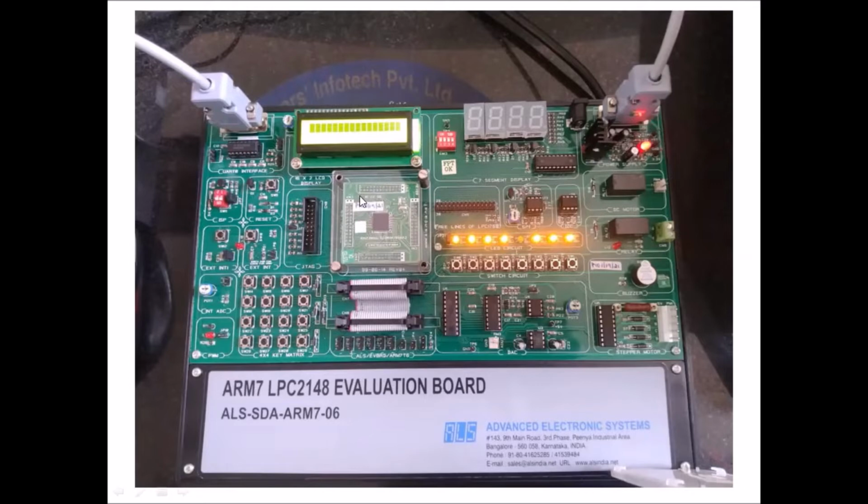So this is the microcontroller. This is the processor, ARM version 7 processor. It is a quad flat package, which means there are 4 sides in the processor, and there are 64 pins in this processor. So 16 pins on each side. We have 4 sides, 16 pins each. If you multiply 16 into 4, it will be 64 pins. I will let you know what these 64 pins are in the coming slide.